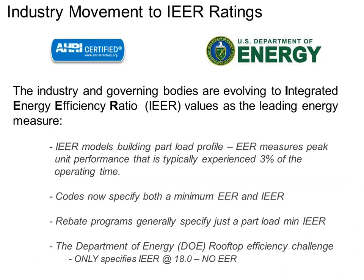All right, so with that in mind, IEER is a big deal. DOE, Department of Energy, has been looking at that as well. It's an important factor. And recently a challenge came out a couple years ago by the DOE to the rooftop manufacturers to develop systems that could do very well in an IEER test. And there were kind of bonuses and spiffs for doing that. And there was no EER requirement at all, only IEER. You're going to see anything related to the Department of Energy going forward, anything related to the codes going forward, and we'll talk about that in a little bit. They're all focused on IEER. Part load efficiency is not important anymore.